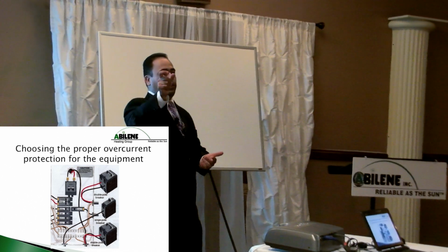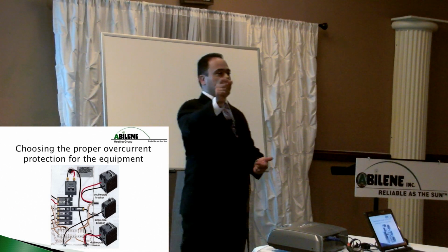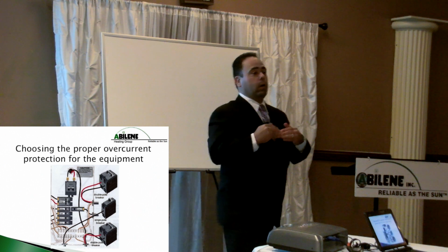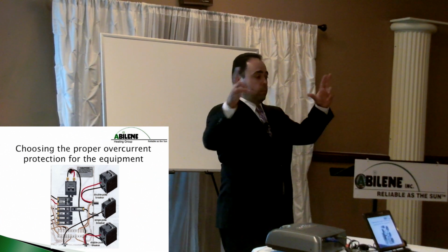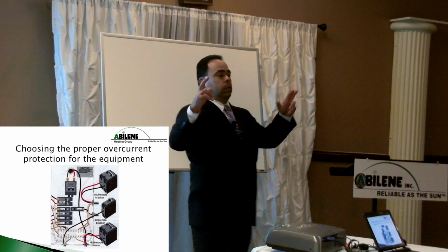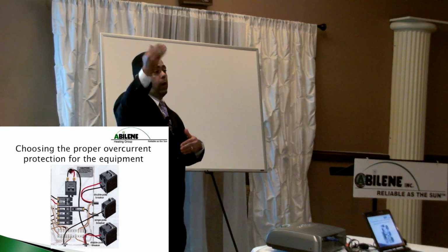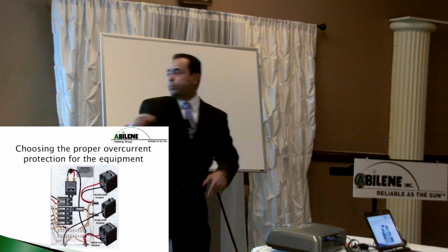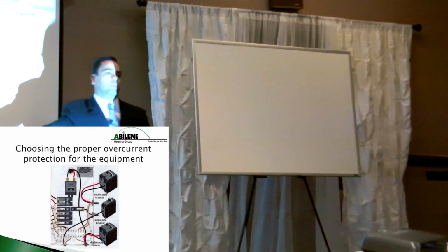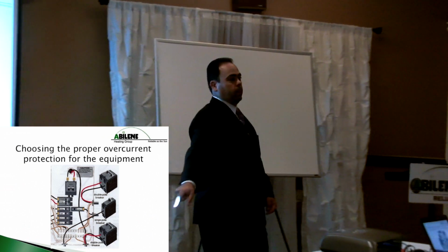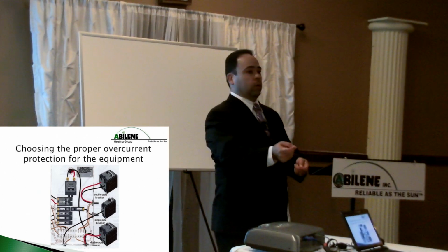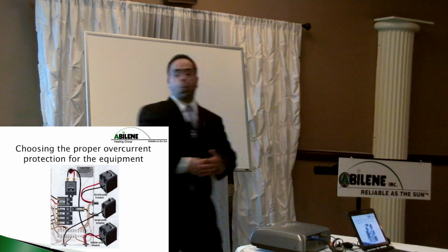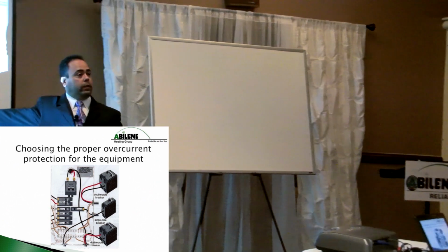If you use a 15 amp breaker, it's not going to allow more than that 15 amps at a certain time. There's a time limit on that, to flow through that wire, and it's going to protect the wire downstream of it, right? So that someone doesn't try and pull 60 amps through a wire that's only rated for 15.